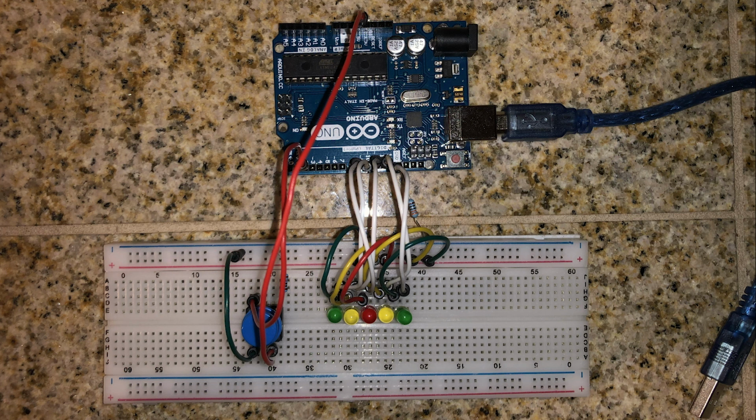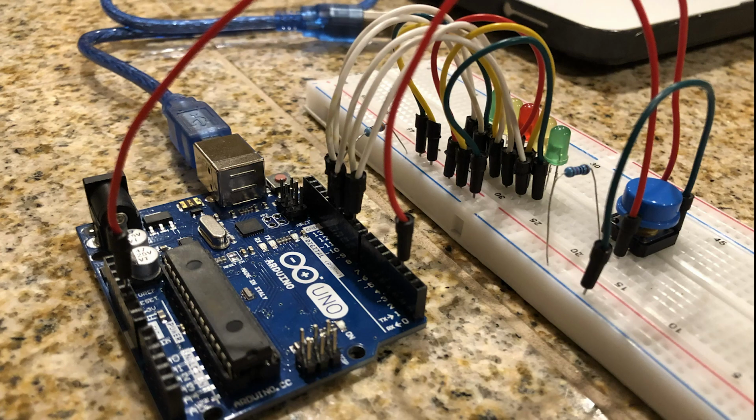While 5 jumper cables will each be connected to a specific pin from pins 9 to 13, then connected to the negative end of the LED. While the positive end of the LEDs will be connected to the positive bank using 5 more jumper cables. Lastly, the 330 ohm resistor will be connected to the negative bank and the ground pin. So this is the top view of the setup, while this is the side view of the setup.